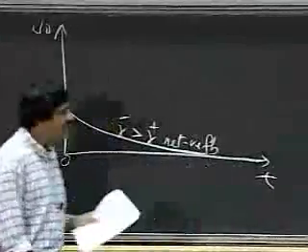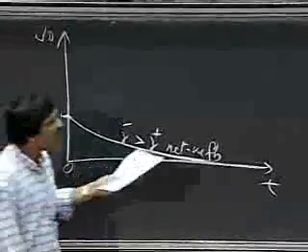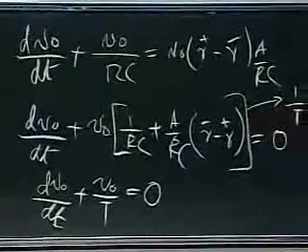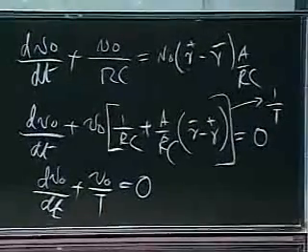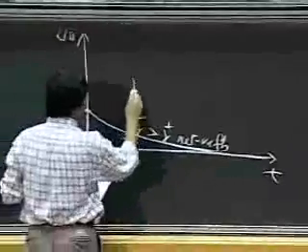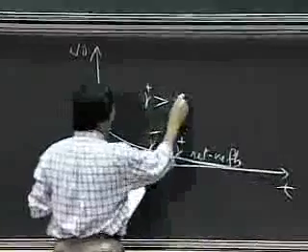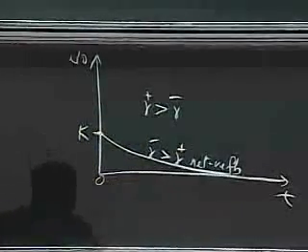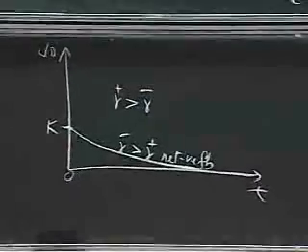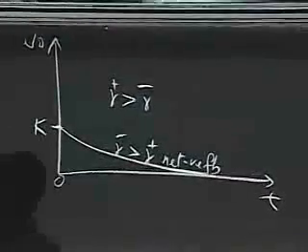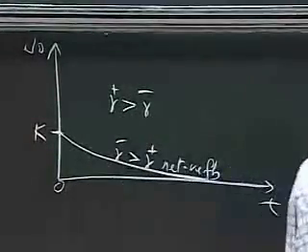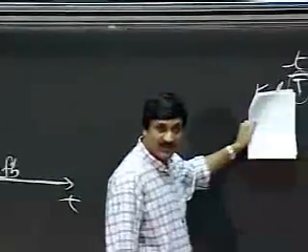So let's take a look at another situation. What happens when the opposite is true? What happens when gamma minus is less than gamma plus? When I feed back more, when gamma plus is greater than gamma minus, the opposite is true. This means that I'm feeding back more to the positive input. A bigger proportion goes to the positive than the negative. What happens then is capital T becomes negative.